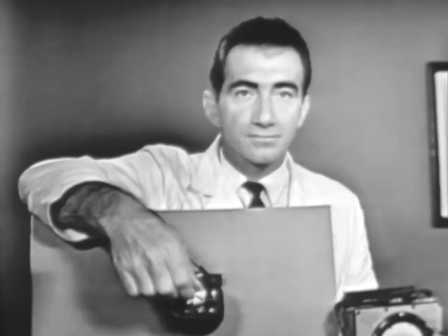That's right. Now, since we put a load on the motor, this fan, in other words, we've caused the rotor to turn slower. Well, how do we generate enough energy to keep that rotor turning? That's a very good question, Bob, and I hope you've got a good answer. Oh, we do. The rotor becomes an electromagnet, right? Right. But how strong an electromagnet is the rotor? How strong should it be? It should be just strong enough to do the job, in this case, to keep the fan blade turning. The strength of the electromagnet is determined by the amount of current that flows through the conductors of the rotor.